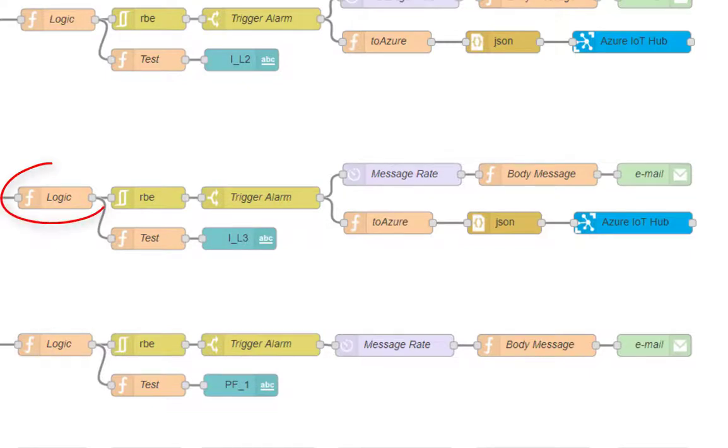The margin values are set up and classified with a function, and the data are sent to the switch only if a change is detected, and if the values are considered critical. The Node-RED alarm has a limit of messages, selected with the delay block. To send the alarm within Azure, the header information must be added in JSON format before the alarm is dispatched.